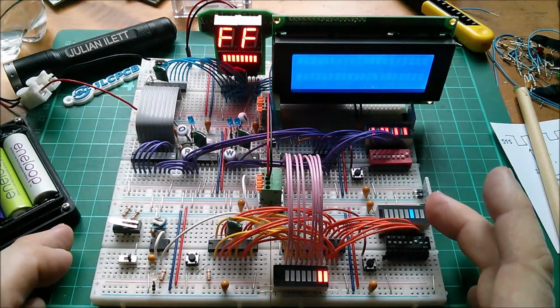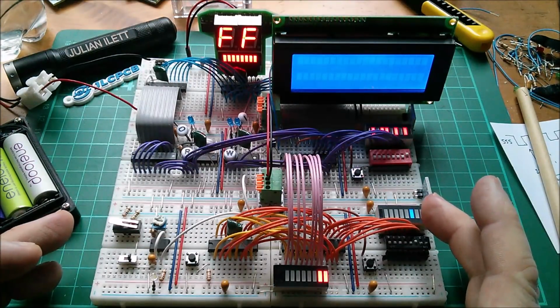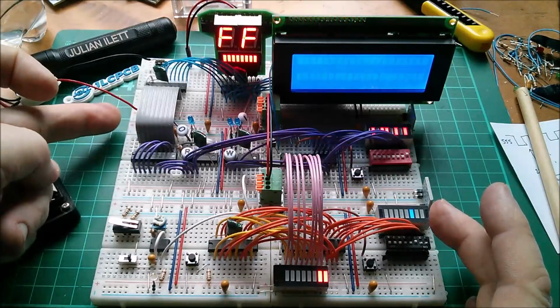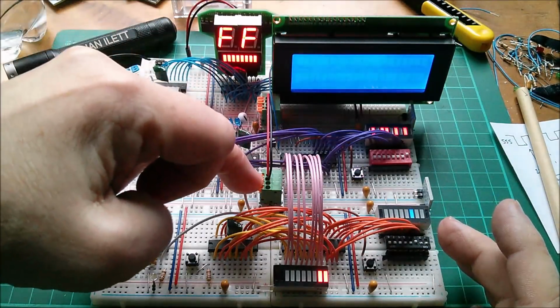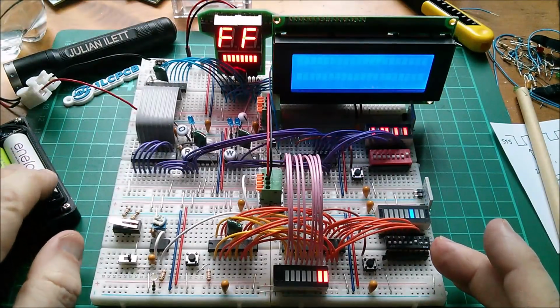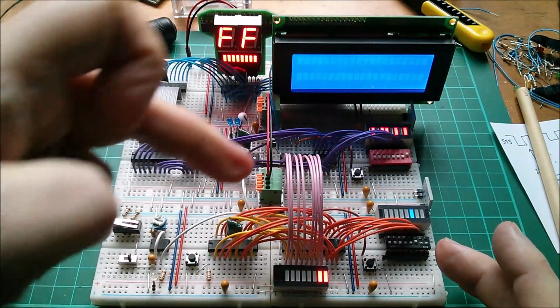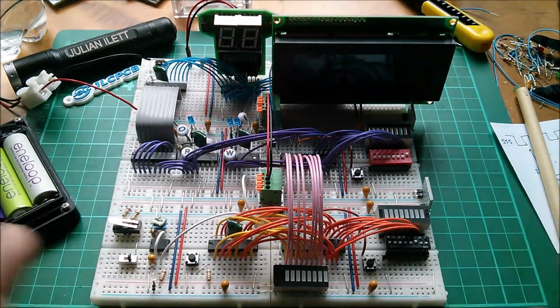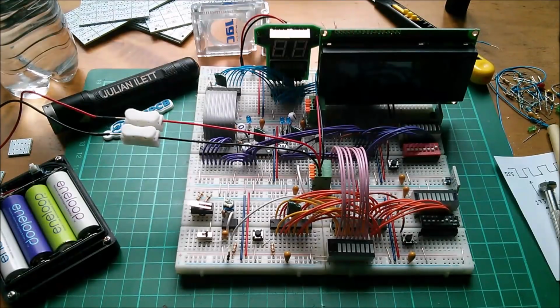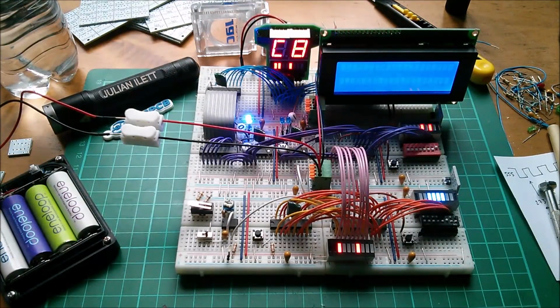This display has got so bad I can't even see what I'm doing now. So I think, because I plugged this in here, that was silly, I'll cut a new piece of red and black wire and poke them in these holes here so that my battery power, assuming my batteries are good, goes straight into the middle of the board. I'm going to do that. So I'm actually going to power off, lose what I've done, come back and start again. Right, let's try that. Switch on.